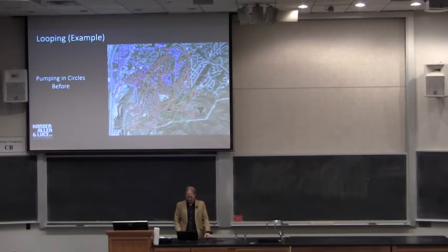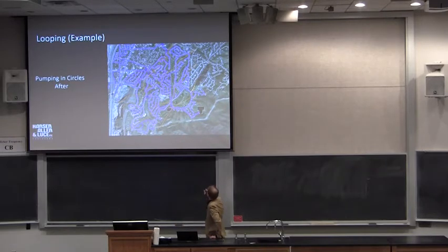So this is after. All we did was tell them to change the PRV settings. We gave them the actual pressure settings because we used the model to determine those. It took 2 guys about 2 hours one afternoon. They switched it, and then this was the result.